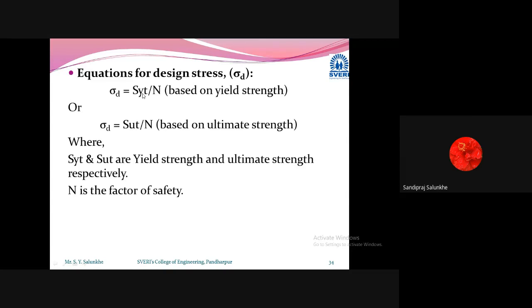Shear, physically it did not shear, then also it is considered as a failure. That means it is not capable of sustaining that load. That is the property of ductile materials. They will not fail, or it will not break into two parts. But before that, they will go to the plastic stage. That means they start to elongate.